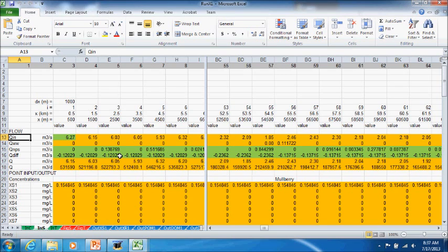So what we have here for each segment is the upstream inflow, the wastewater discharge, and the non-point source discharge. This is the runoff unaltered. Okay, this is what you would get from runoff, and then the difference, which is essentially the agricultural or other or municipal withdrawals of water from the river. And then the model does a flow balance here to balance the water.